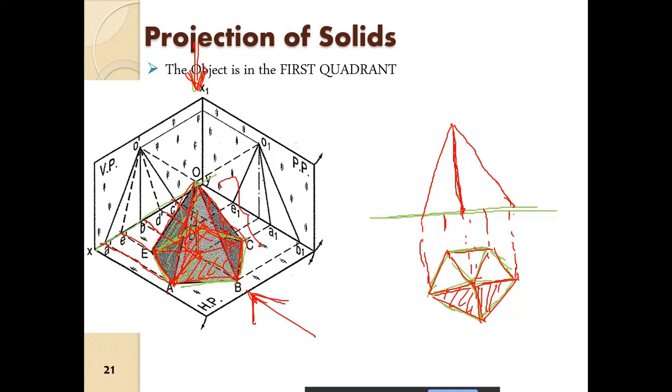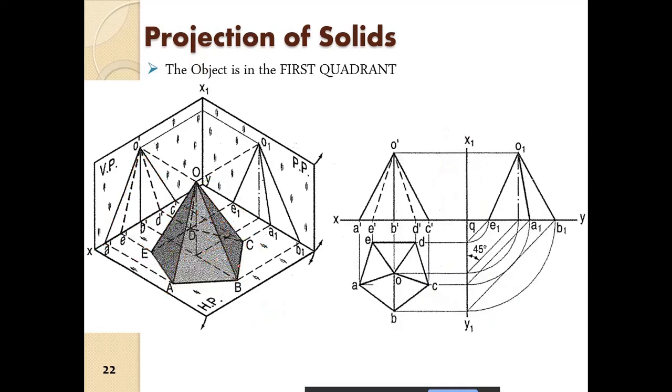And we have to mention that there are some hidden surfaces as well, so dotted lines. These three surfaces will be hidden, so we have to mention that they are hidden. That is why this is what the front view looks like. This is the front view projection, and this is the top view, which is beneath the pyramid. So this is the solution here.